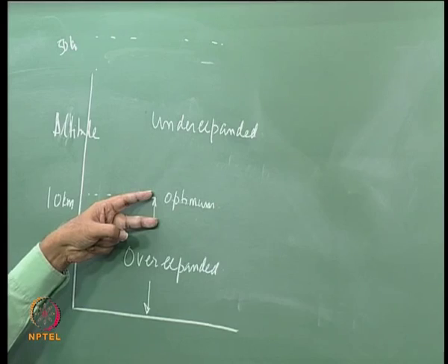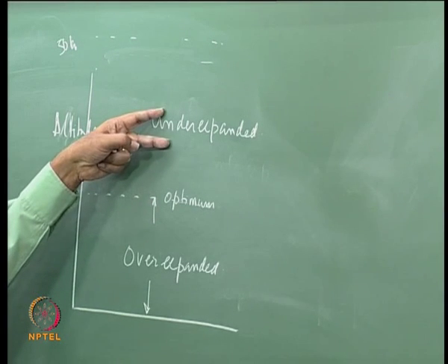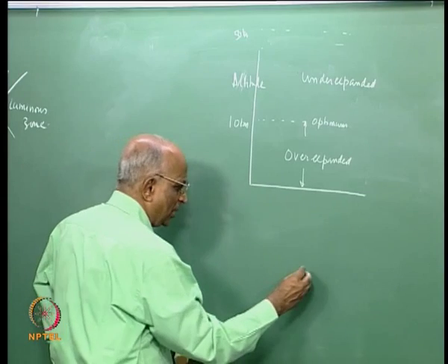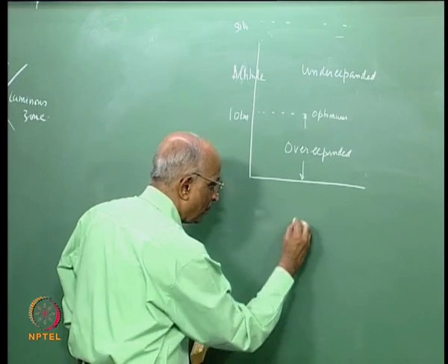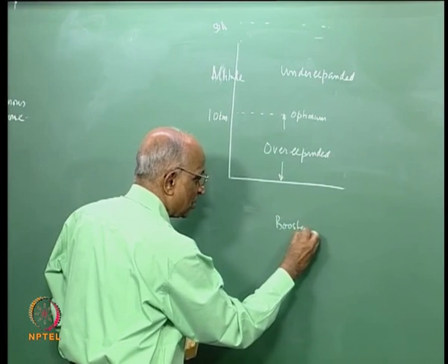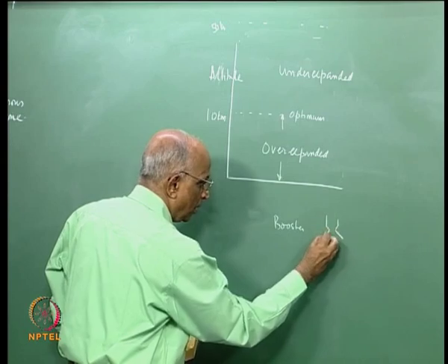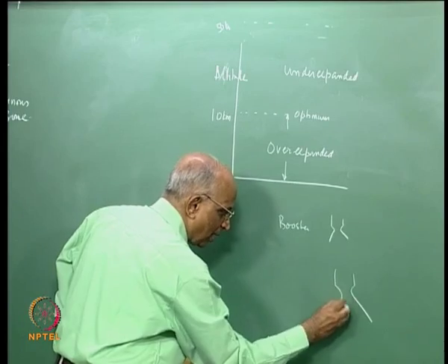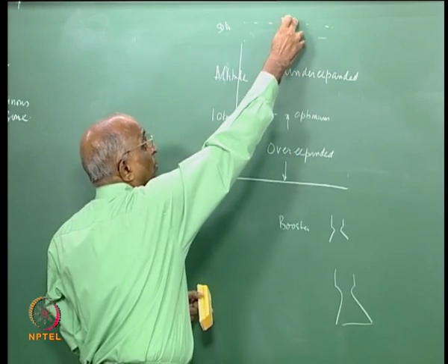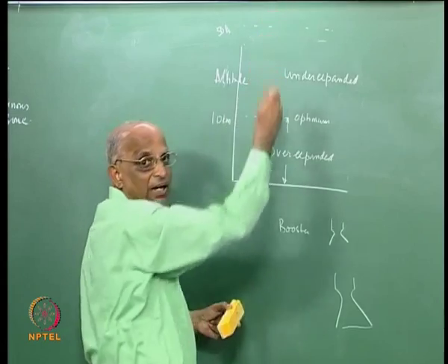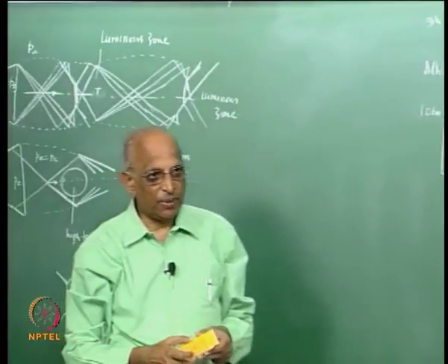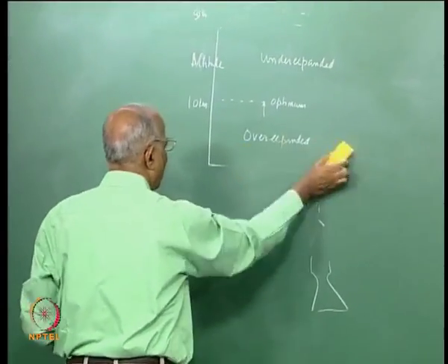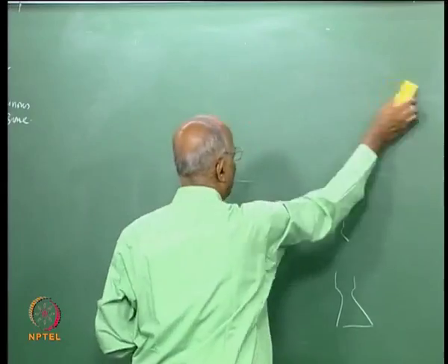that a given nozzle operates either in an under expanded mode or over expanded mode, but we try to decrease it. As you would have seen in the earlier figures, a booster stage has a small nozzle, whereas if the rocket is going to fire at high altitude, I will design it with a larger nozzle such that the optimum shifts to the higher altitude, and this is something which we have to keep in mind. I think something more we must remember while we are talking of under expanded and over expanded nozzles.